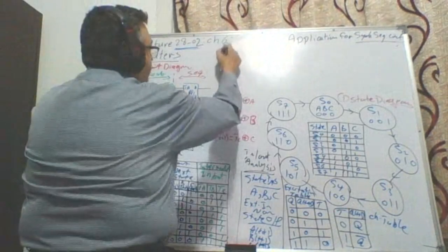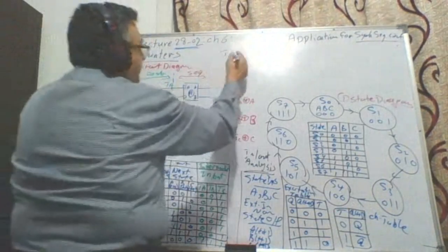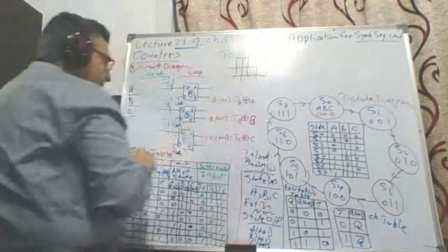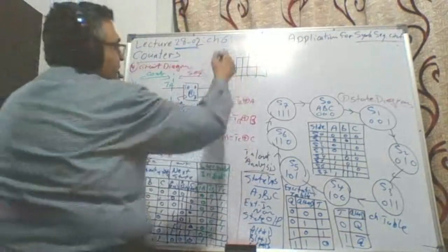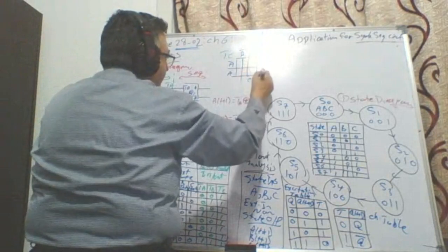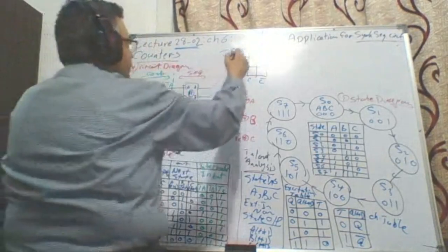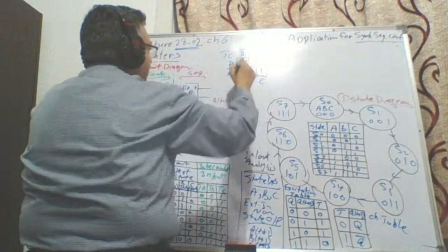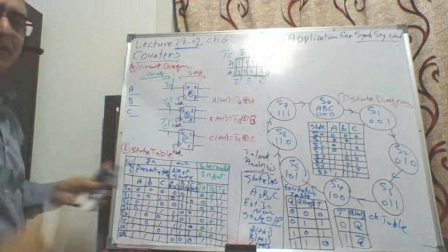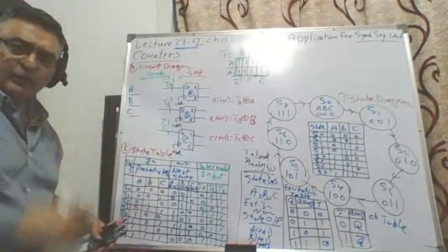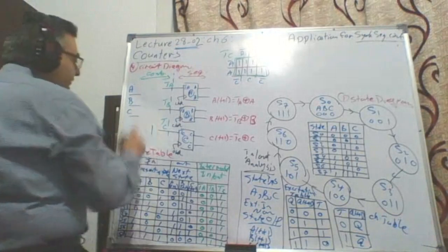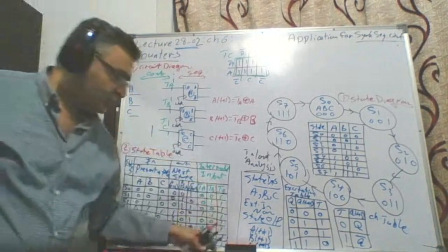Even if I did, what would the K-map for TC look like? Here is the K-map, okay? But remember that this K-map contains all ones. So I expect that this K-map will be all ones. 1, 1, 1, 1, 1, 1, 1, 1. Where is the contour? The contour is gathering everything together. And X, X bar, A bar kicked out, B kicked out, C kicked out. We discussed this before. This is the unity function. So TC simply equals 1.